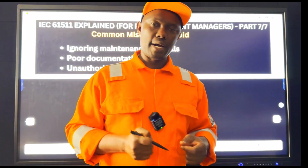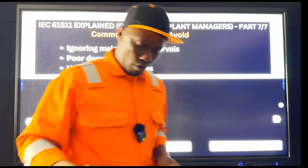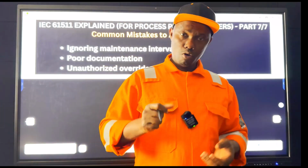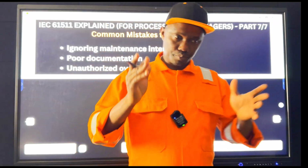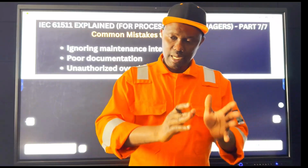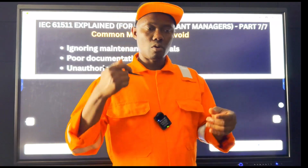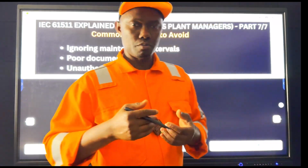Unauthorized overrides. This is one of the common mistakes to avoid. It has to go through the approval process before an override is put in place. And once the purpose for which it was put in place has been achieved, or for whatever reason it was approved, at the right time when it should be taken off, the override should be taken off.